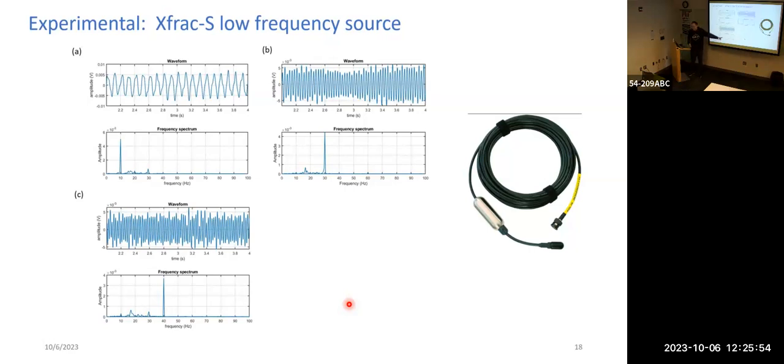First is 18.4, which is the largest peak and always exists, and some peaks around 30 hertz, and the low frequency signal always shifts from 0.something hertz to 10-something hertz. It changes because of the AC and the pipe system, and when somebody switches the pipe off and on, it will generate a different type of noise.